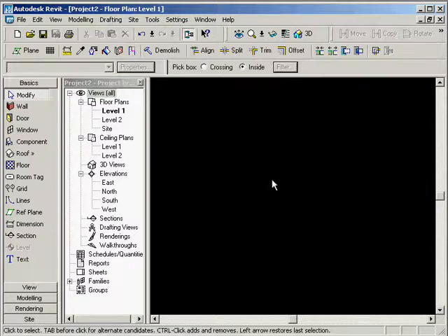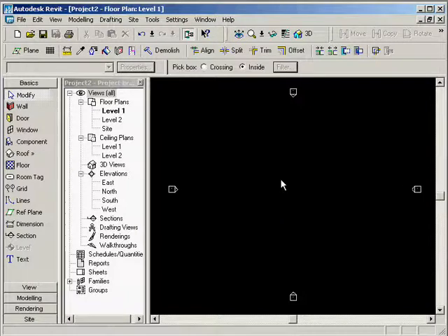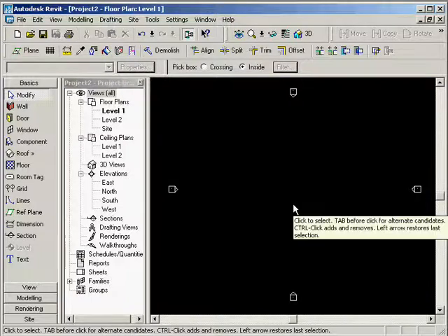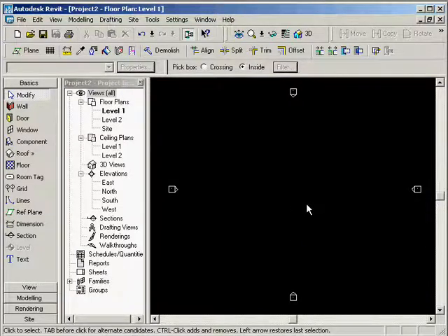So just a little review on some of those objects right there, and I'm just going to delete that. I'm going to use my zoom button here. A couple of quick commands: I'm doing ZE for zoom extents, and I can also just click up in here. So we do have some Revit short commands. If we go into the help and look for shortcut commands, there's a txt external file which you can edit, similar to a PGP file, and change all your shortcuts. So have a look for shortcut commands, and we'll be doing a few of them as we go through this.